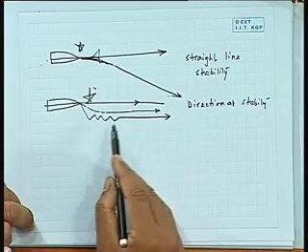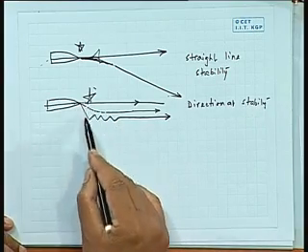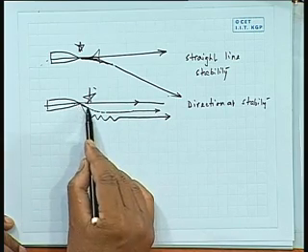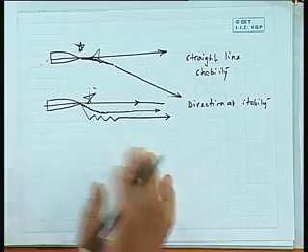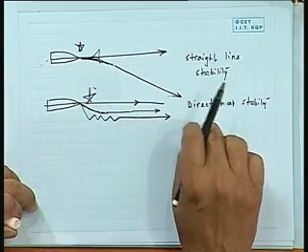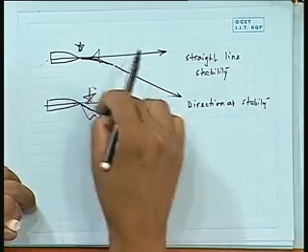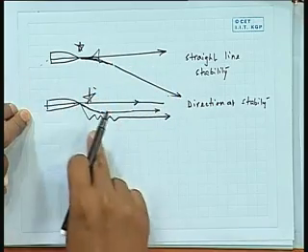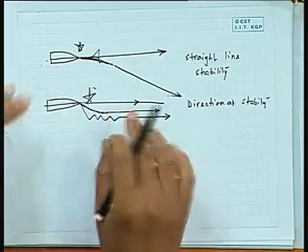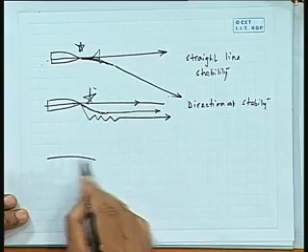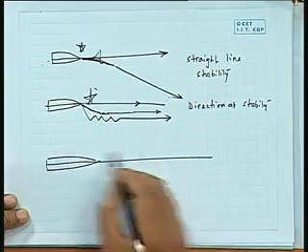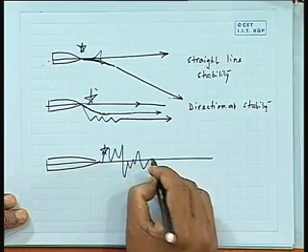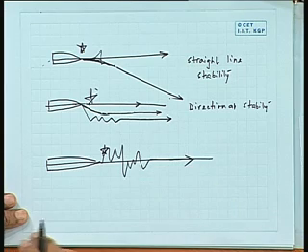And here also there can be two cases. Normally the disturbance would have caused an oscillation and then it goes to a straight line, or it could have simply deviated and it goes to a straight line. Both the cases are examples of directional stability, but the mathematics of the forces differ. One can tell from the hydrodynamic characteristic whether it will be this type or that type, whatever. These are directional stability. The third one is that going on a straight line, you give a disturbance here, so it actually goes to this thing, but ultimately it comes to again a straight line when the disturbance goes away.